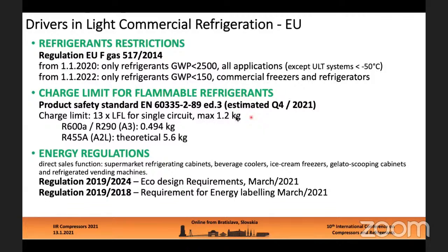For instance, for propane, it's allowed to apply a charge of up to 500 grams, but for A2Ls, refrigerant R455A, theoretically 5.6 kg can be used, but the standard is limiting it to a maximum of 1.2 kg.